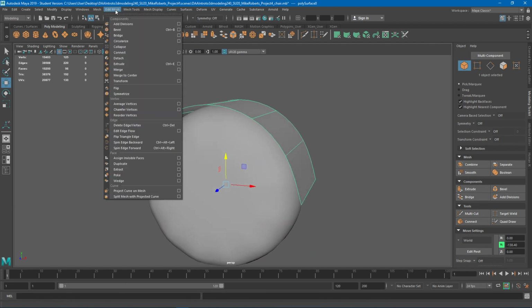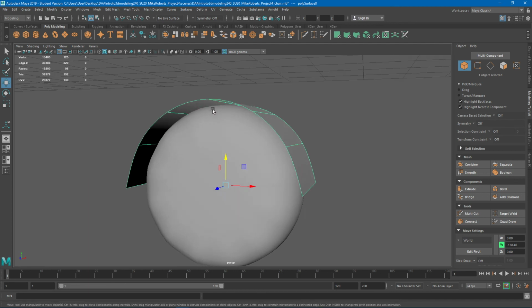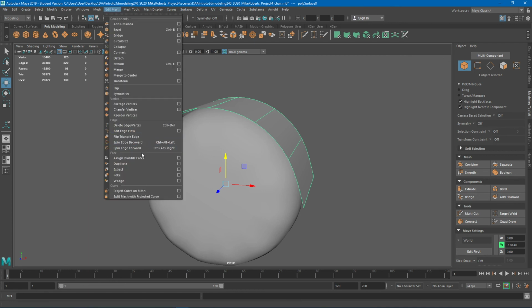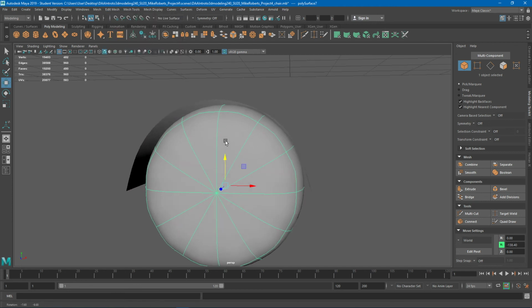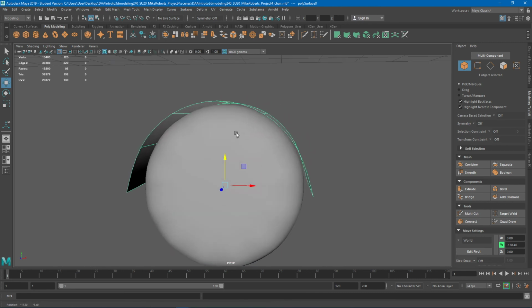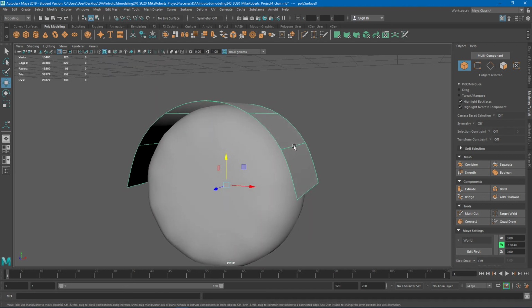That's what that edit mesh duplicate does, right? Extract would have cut, right? We saw that on part of our chair, on our door, right, where we wanted them to actually separate it, and there was actually a hole left behind, right? Here we just wanted to copy, right? So edit mesh duplicate is like copy in Photoshop, right? And edit mesh extract is like cut, right? Duplicate just copies it, so the original has everything intact still. There's just new geometry based on that selection. Extract would actually rip this apart off of that and leave a hole behind. And both are great and have their appropriate uses.